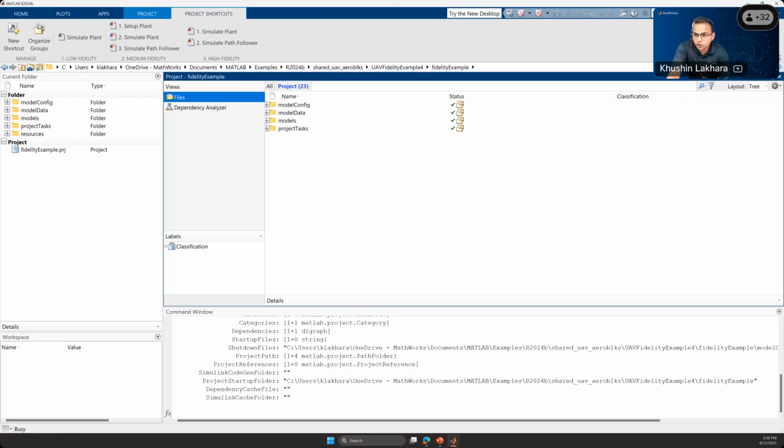True. So when we go for the photorealistic simulation, the benefit of it is you can actually click pictures of the environment and use them for your model development as well. Like you want to train your neural network, or you want to train and test your image processing system. For all these purposes, we need it. Photorealistic simulation has its own needs, but there can be a time at the early stage when you are not still implementing your guidance algorithm, or you don't have a camera sensor on board. You may be good with some scenario which depicts obstacles, maybe just some 3D buildings, which can be some rectangular boxes or cuboids, or maybe some cylindrical objects, right?